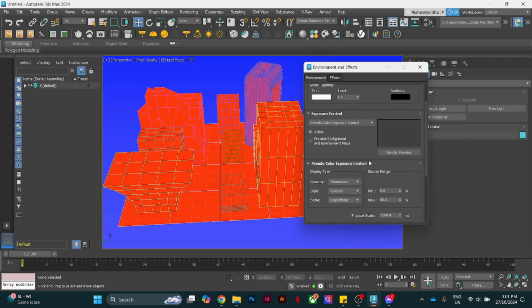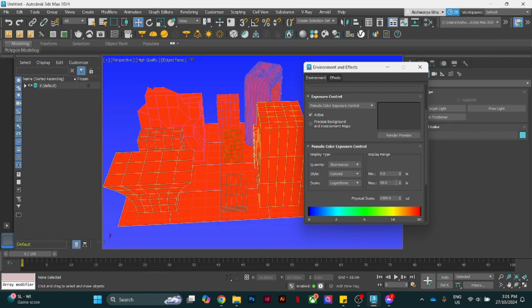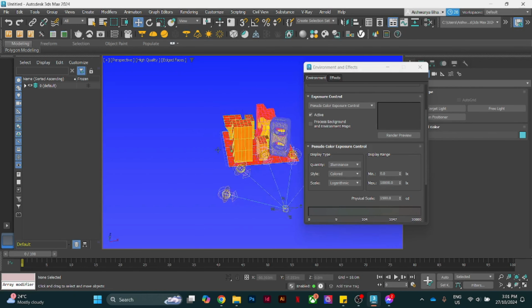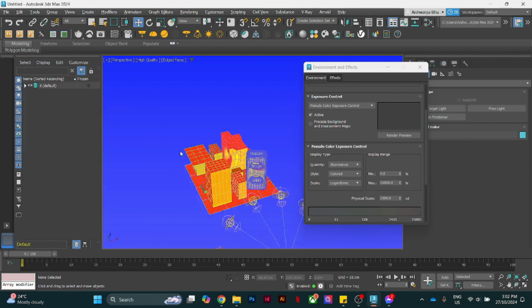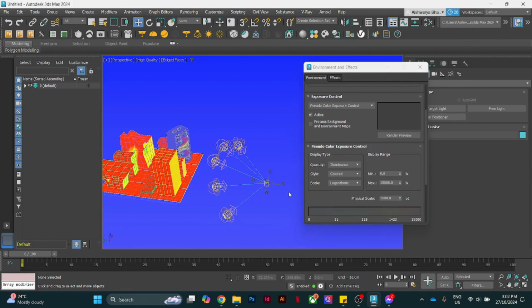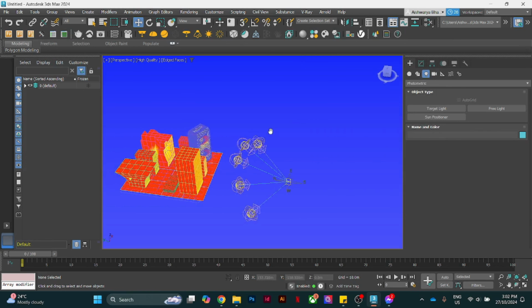For it to be a bit more detailed, you need to change the range from 50. Let's try to make it 1,000. You can see some differences here, but it's still not very prominent. So let's try it again at 1,000. Yep, and you can see a bit more of it. Maybe we'll make it 15,000. Alright, and then this is how we can do your sun analysis.